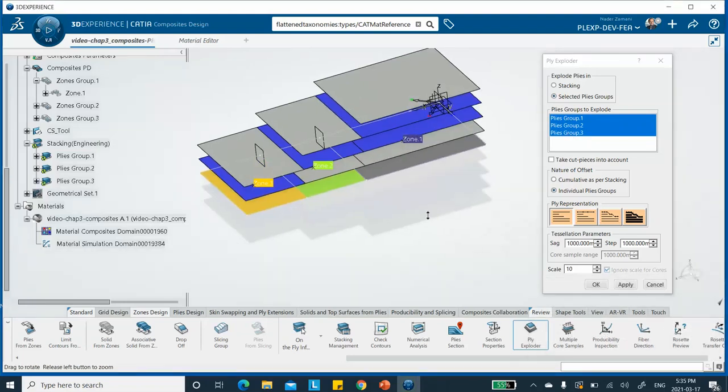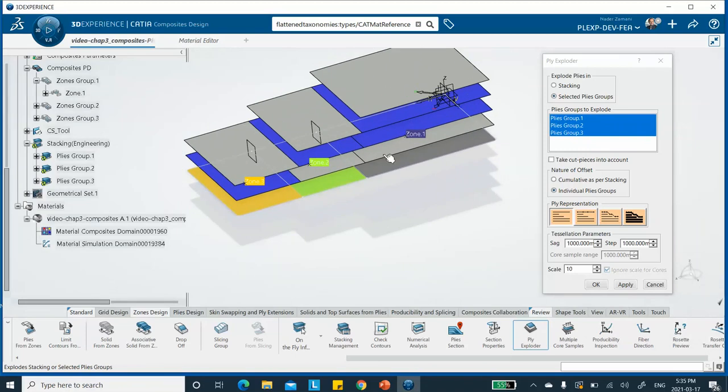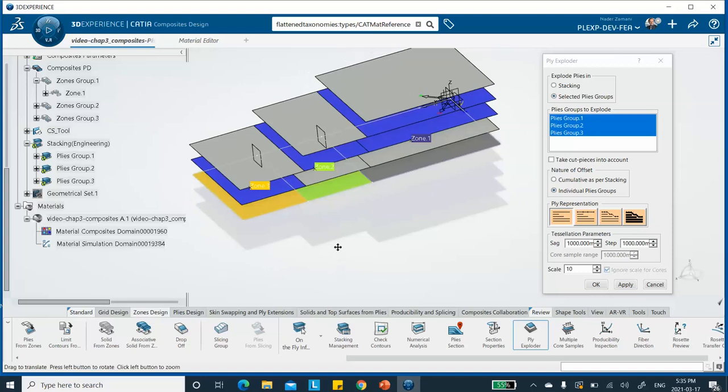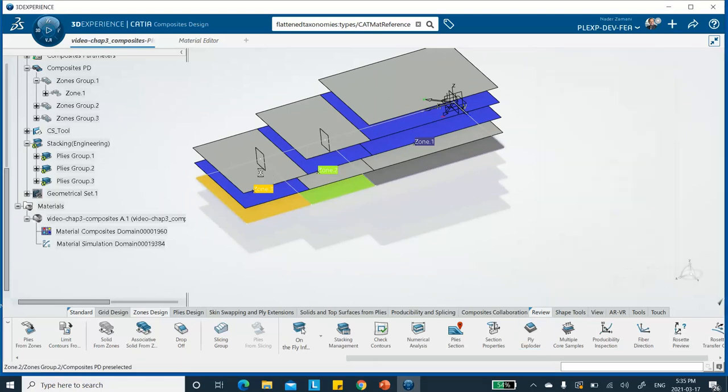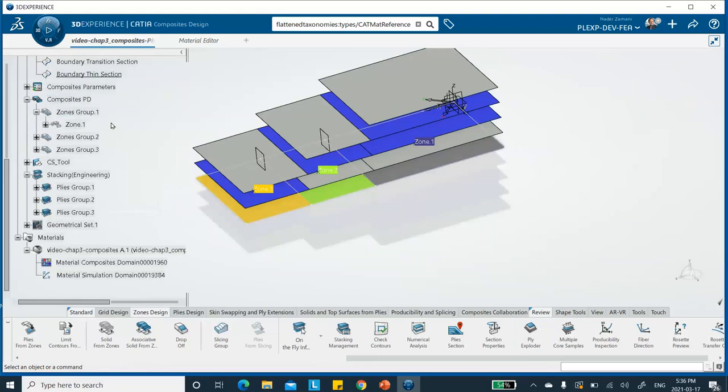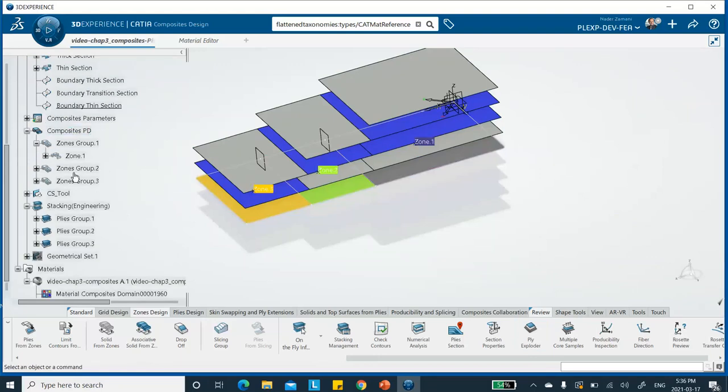You see, they're all created, but the position of them is not right because we want a 90, 0, 0, 90. And in spite of the fact that I put it in that order when I was creating my laminates, when you do the zone method, it does it according to its own algorithm, okay? So I have to change these things. Now, to change these, although it's inefficient, I'll show you how I do it because there's only 9 of them that I've got.